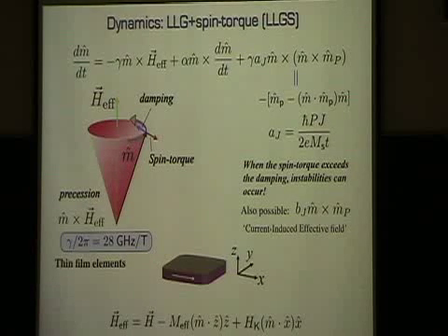So here the threshold of the current should be proportional to the damping coefficient. That's right. It's proportional to the damping coefficient and also the frequency of precession. I'll write down the expression on the next slide. It depends actually on the forces in the ferromagnet, the energy of the ferromagnet, the micromagnetic energy.